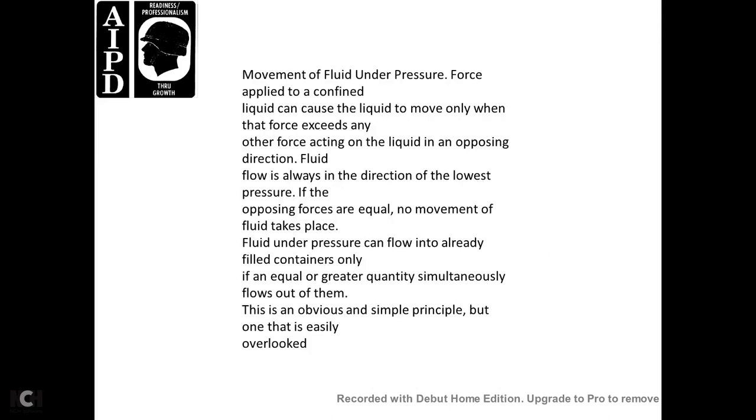Movement of fluid under pressure. Forces applied to a confined liquid can cause the liquid to move only when the force exceeds any opposing force on the liquid. Fluid always flows in the direction of the lowest pressure if the opposing forces are not equal.